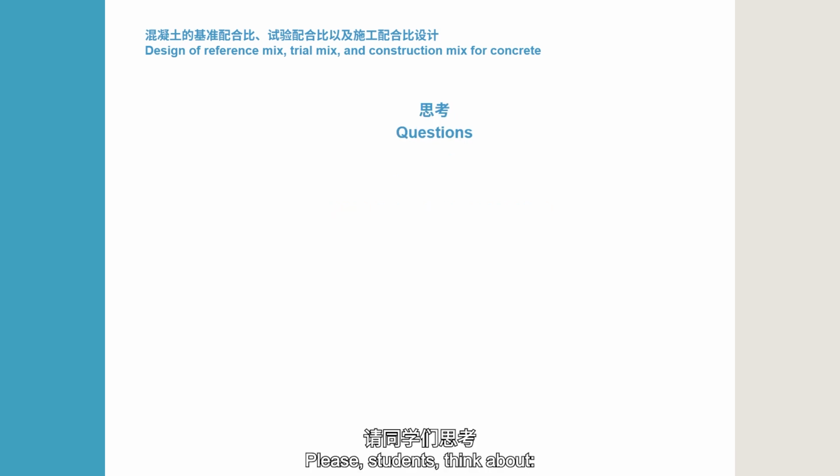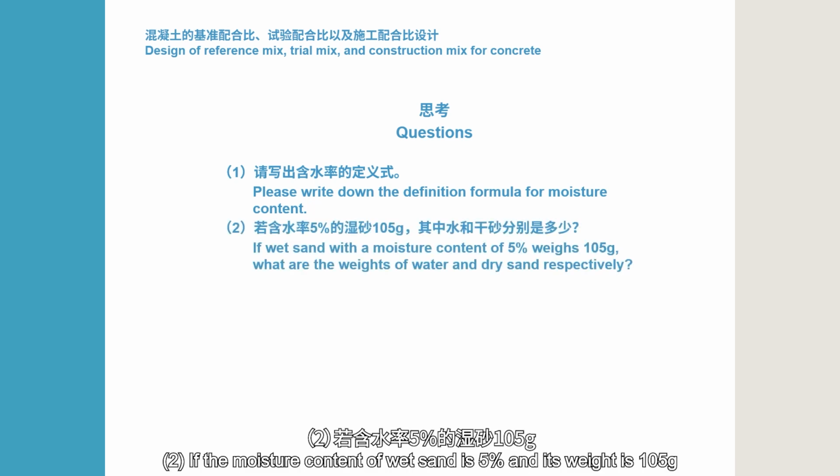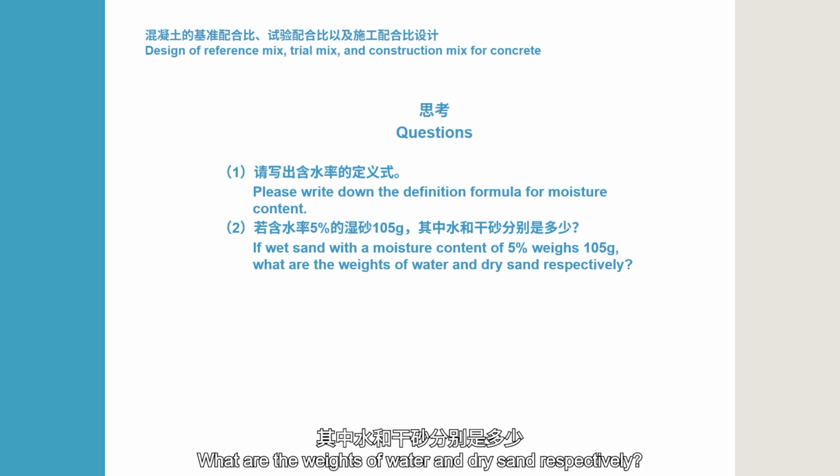Please, students, think about: 1. The definition formula of moisture content. 2. If the moisture content of wet sand is 5% and its weight is 105 grams, what are the weights of water and dry sand respectively?